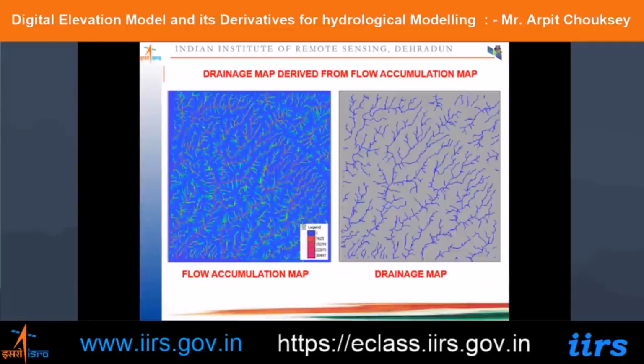Now comes to the another parameter, which is the hill shading, where the shadow filter has to be applied. It is the standard linear filter which works in a 3x3 environment, and the value of matrix are as shown. And the main purpose of hill shading filter is that it eliminates the direction. The illumination direction can be varied by mirroring the values of the matrix.